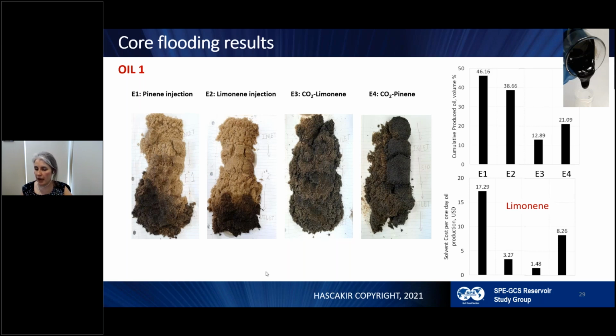produced oils. However, if you're talking about produced oil quality, if I just make the sulfur disappear, no, I am not God. So if there are some components in the oil, there is mass balance, you cannot make them disappear by just injecting a simple solvent, but you can change their structure and move them to the heavier fractions. The only thing that I can say right now, we reduced the asphaltene fraction, the heavier fractions, and we created more aromatic hydrocarbons.